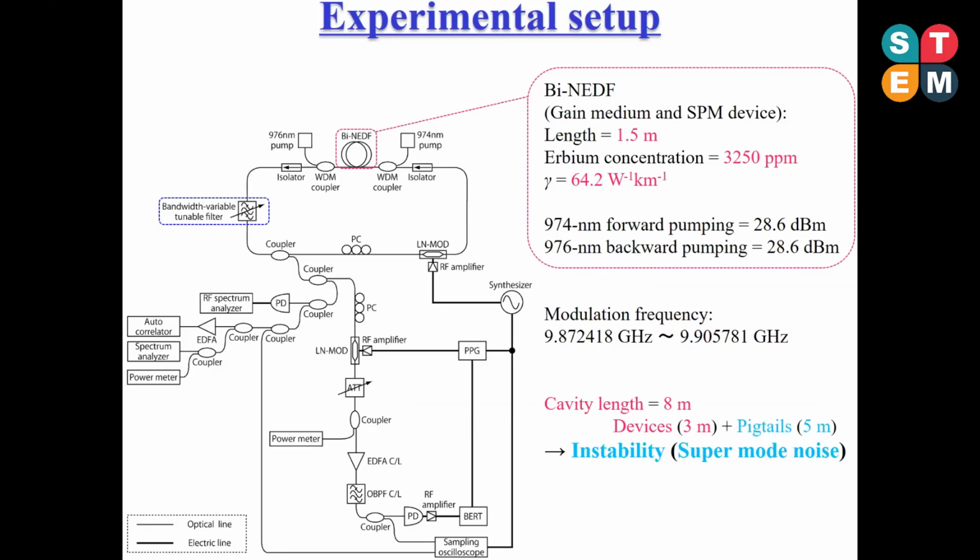In this experiment, to suppress the supermode noise, we also used the self-phase modulation in the 1.5 meter long bismuth oxide-based nonlinear erbium-doped fiber and the spectral filtering by a bandwidth variable tunable filter supplied from Alnair Laboratories Company Limited.